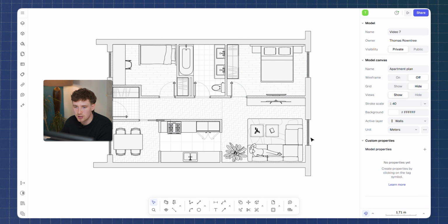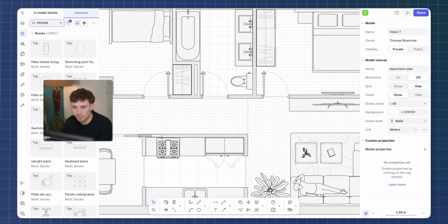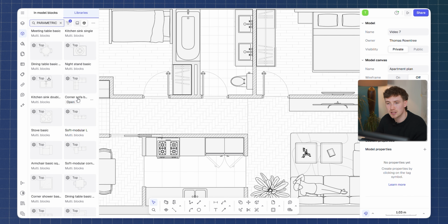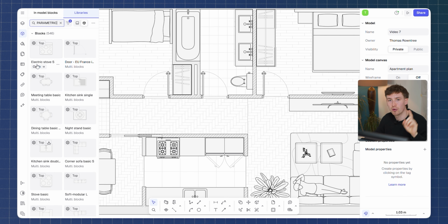And then if you want to add a parametric block, you can head to the top left corner here. Now, parametric block works really well in that you can then start adjusting and essentially scaling and contracting your components without distorting the material geometry. So things extend or widen or shorten. Now you can find those in the block library again. And the best way to find these is to head to the block library. You can then search for a parametric block.